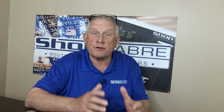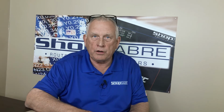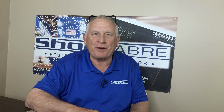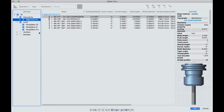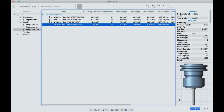Now we're ready to start actually creating our toolpaths, and we'll do that in the order that things will occur. First, we drill holes, then machine the dados, and finally cut the part out. Okay, let's start by selecting drill. And it brings this screen up here, and you'll see a lot of different stuff here, and we have to fill this out. Let's select our tool. So our tool is going to be, there it is right there.